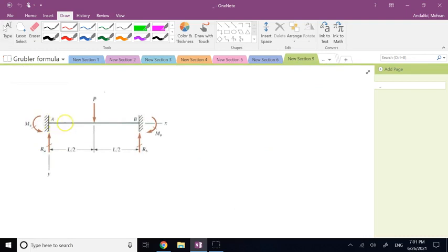So here I have 1 member, just this beam here, from left to right, from A to B. That's all I have that can move. And so here n minus 1 is 1 simply. I only have 1 member that can move, but I have a rigid connection here on the left and a rigid connection on the right. I have 2, 1 here on the left, 1 here on the right. And each rigid connection takes away what? 3 degrees of freedom.